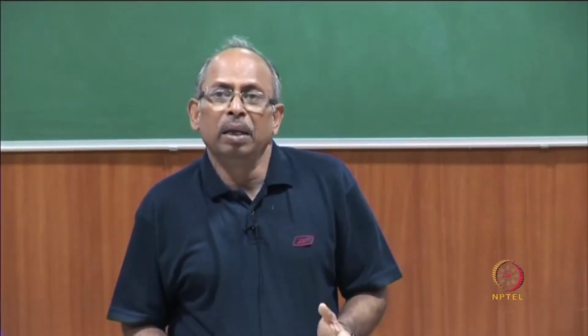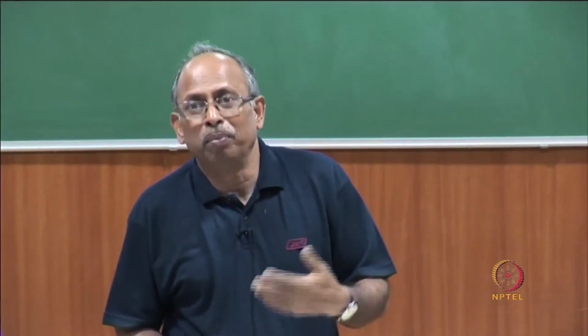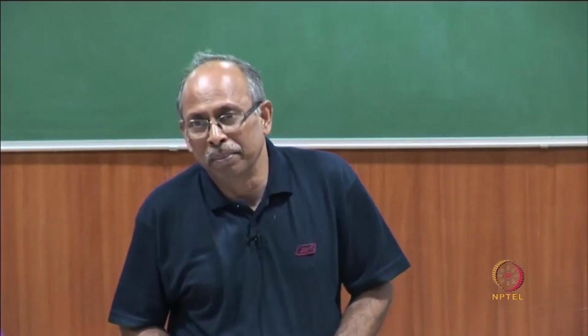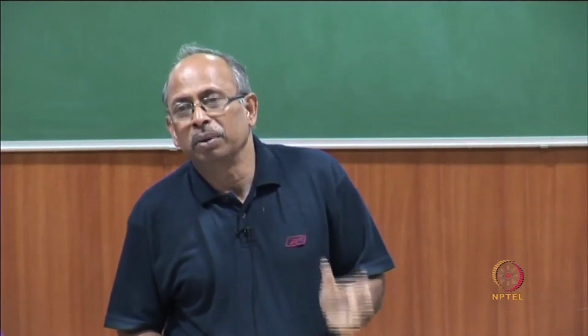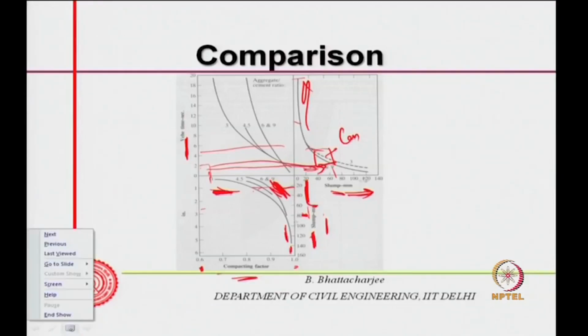Similarly, for self compacting concrete, there is no question of using VB time, or for pumpable concrete, no question of using VB time, not even compaction factor. So, it will be slump and similar kind of thing. So, that is how we compare different tests.